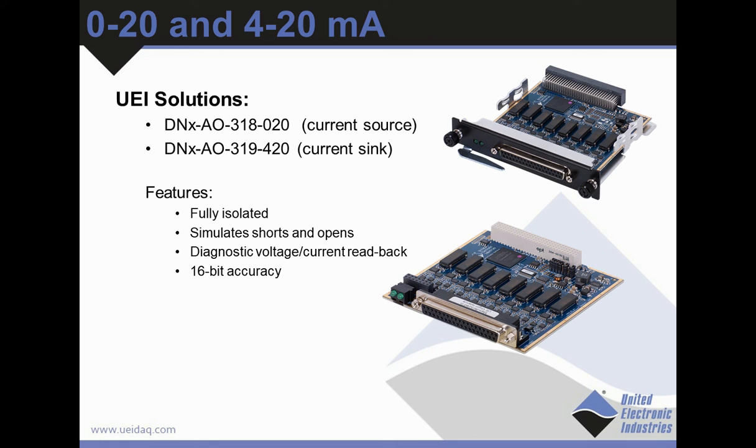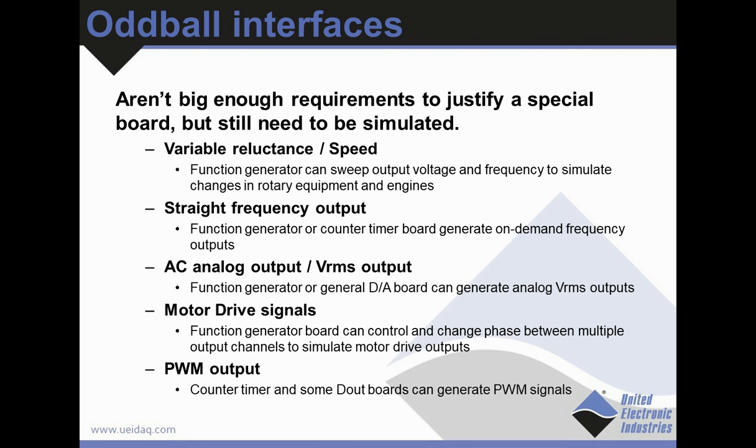As you might expect, we have a couple of solutions for 0 to 20 and 4 to 20, one sourcing, one sinking. They're fully isolated. They simulate shorts and opens. They're 16-bit. They should work fine for you. I don't want to spend any more time on them.